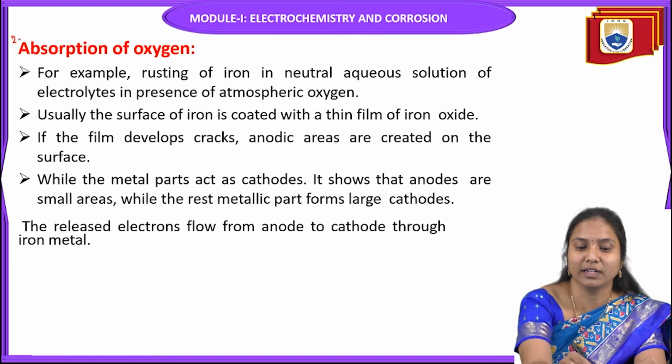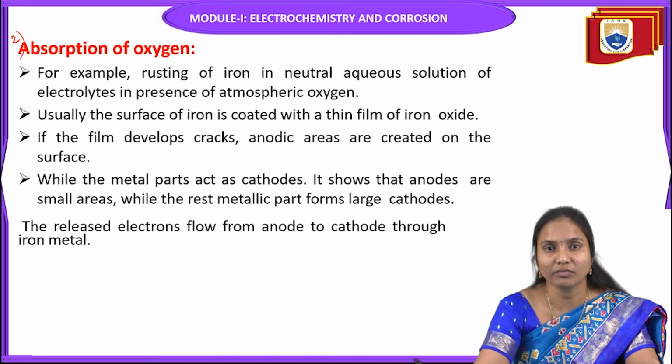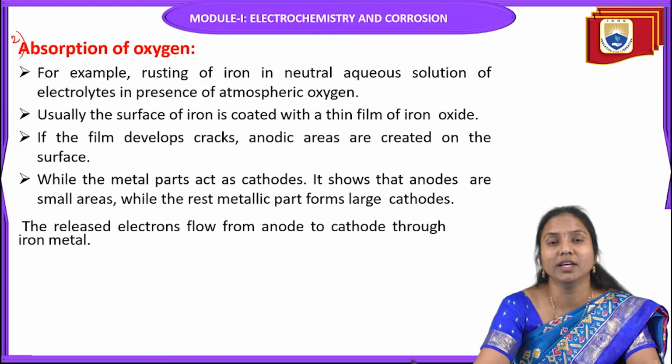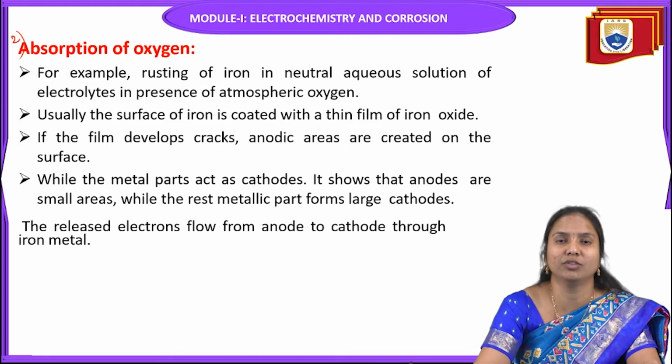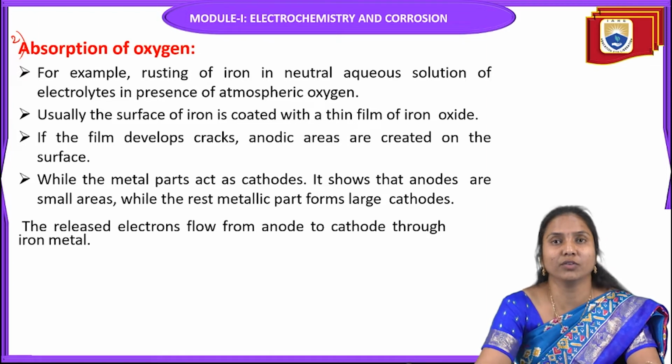Now let's discuss the second type of corrosion, absorption of oxygen. Generally this type of reaction occurs in a neutral medium. Neutral means something like water or aqueous NaCl solution. So when the metal interacts with an aqueous solution or neutral medium, this type of corrosion occurs.